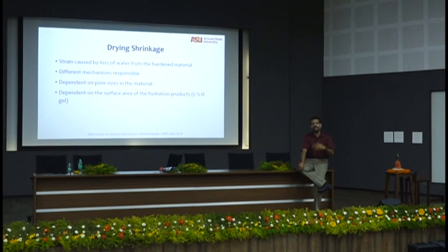We say, I pulled a material with a force of 10 newtons. You cannot pull anything. You cannot push anything. It is your feeling. The MTS testing machine guy will come and show you. You cannot pull the steel rod. All you can do is to apply a deformation to the steel rod. All you can do is to apply a displacement. All the material sees is just strain or displacement.